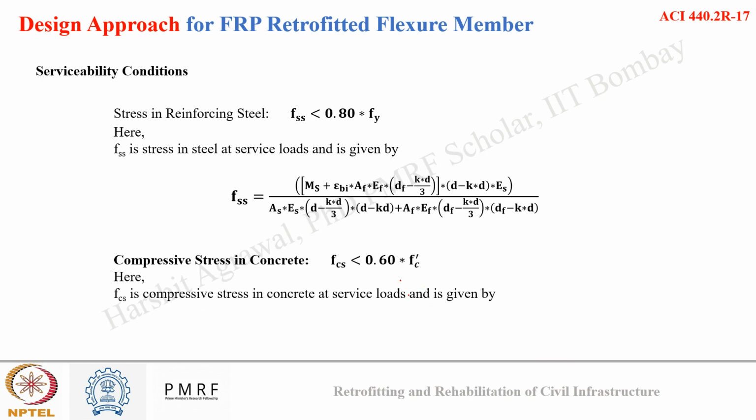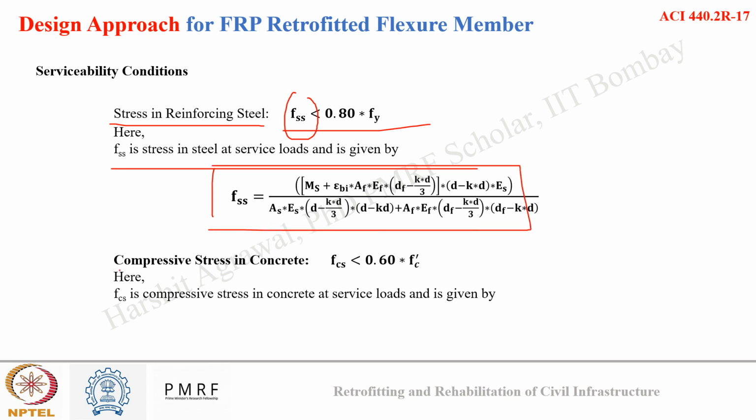And later on we can check for the serviceability conditions also. So the stress in reinforcing steel should be less than 0.8 times Fy. And for determining this Fs, at service load we can use this equation, and for compressive stress in concrete this equation is followed.